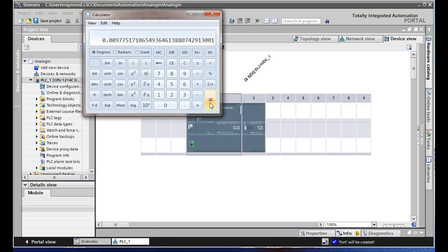So what I would have to do in the Allen-Bradley PLC is take my input, right? You understand? And then I would have to reference that to an actual value. Does that make sense? So I would calculate the transfer function, and when I got a number, I would multiply it by the transfer function and make it mean something like 32 degrees or this or that, right? Does that make sense? So what we're trying to do is get a count over to a unit that we're dealing with.